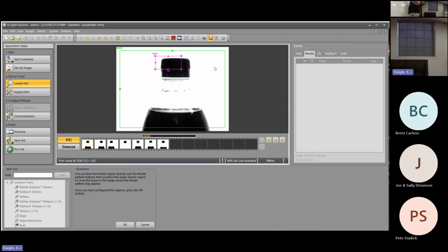A datum is like when a machinist wants to measure a part or put it into a vise, right? They need a fixed jaw that they can smack it up against and make a measurement off that part. Or a fixed part which they can indicate their vise on, and then they got a precise measurement how far over they've gone from that, right? So I want to create a datum. I'm saying, look, this is my datum. Every part should have a cap, and every part should have a cap with a little 90-degree bend in it. I'm going to use that as my datum, all right?